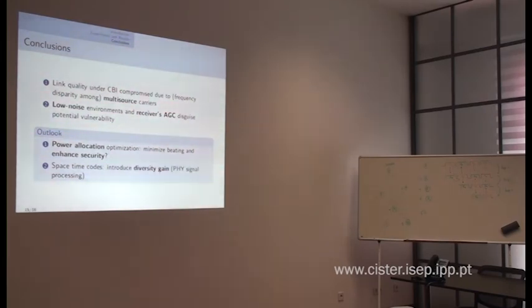have the right power imbalance, and then you can reuse some of the nodes in the network to transmit some noise or a corrupted signal in such a way that everywhere else, except those points where you want to receive, it is going to be very difficult to decode a signal. And that will give you a side effect, which is that you avoid the eavesdropping.